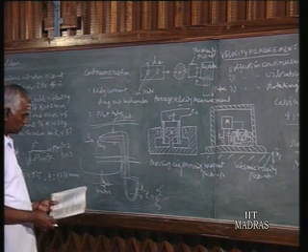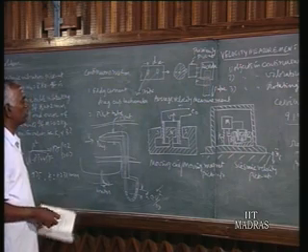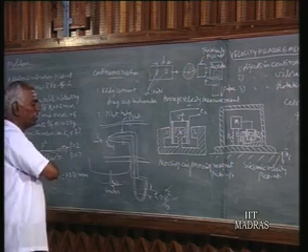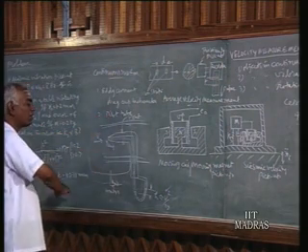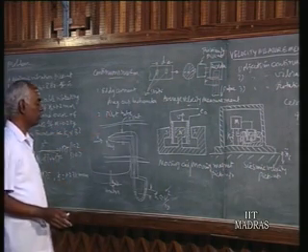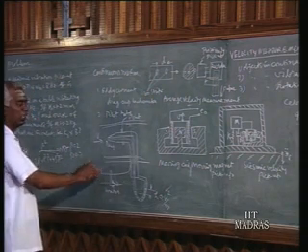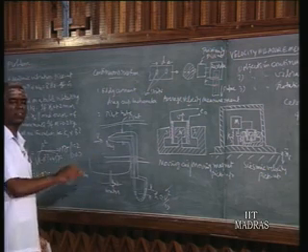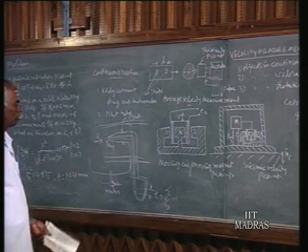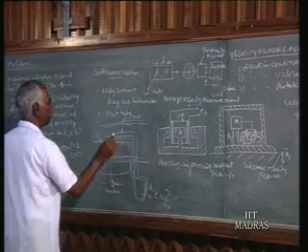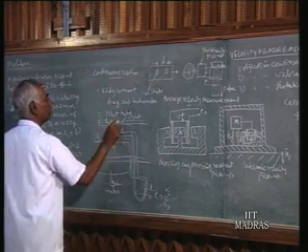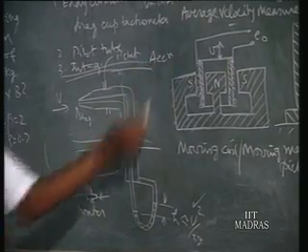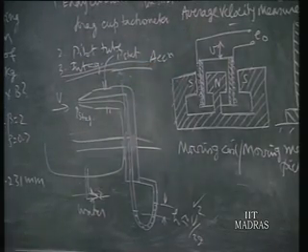And the third method is we have got the accelerometers. You can also mount an accelerometer on a ship. So when it measures the acceleration of the ship, you integrate that, and then it gives rise to the velocity. So by measuring the acceleration and integrating that acceleration, you get the velocity for the ship. This is the third method, integrating acceleration. Fourth method is the Doppler effect.